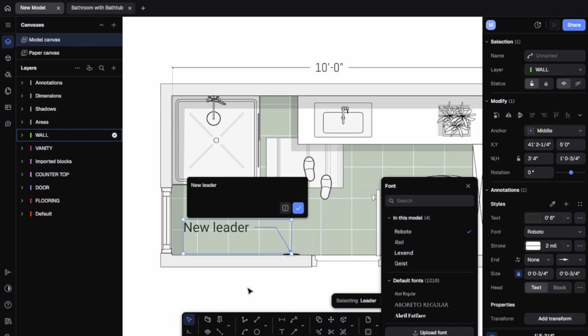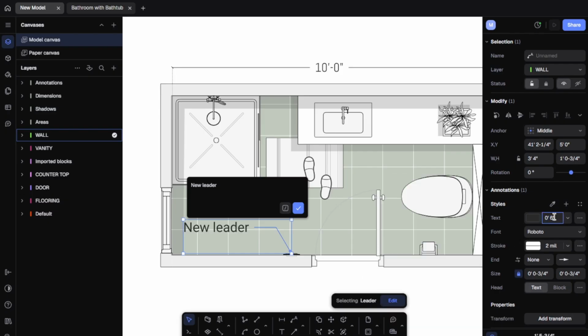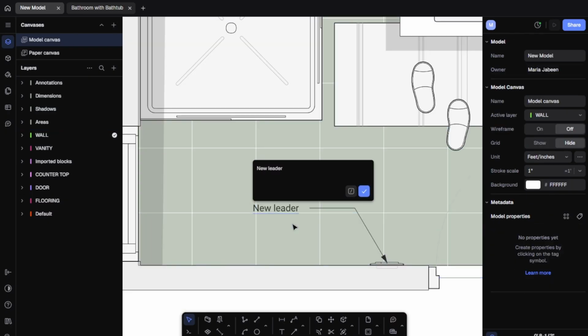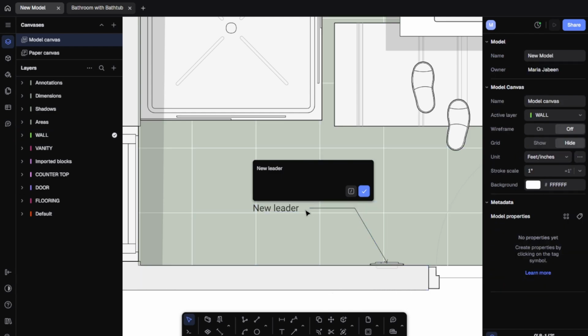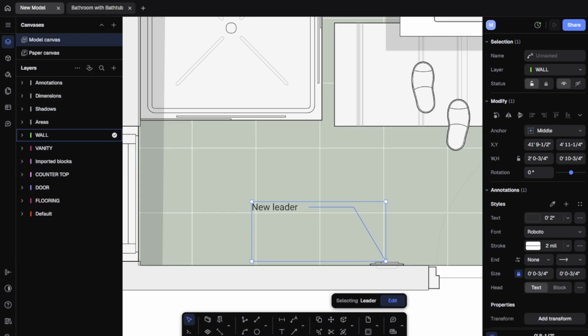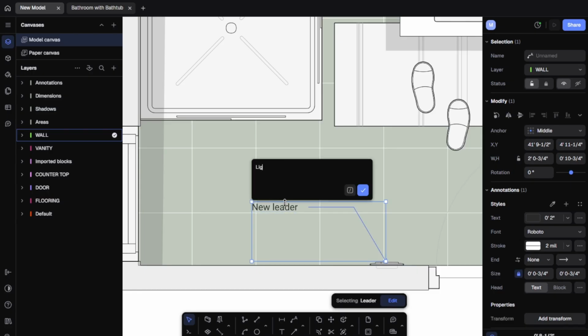Once the drawings looked how I wanted, I exported them to a clean PDF. I set the scale, page size, margins, and included a custom title block with the project info. You could present this to a client or submit it to a contractor. It's clear, legible, and professional.